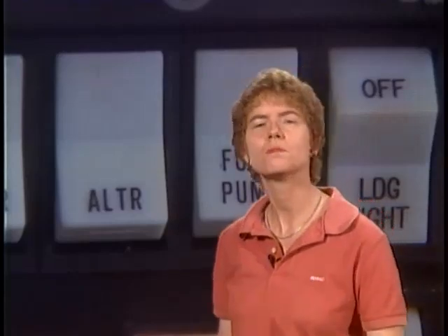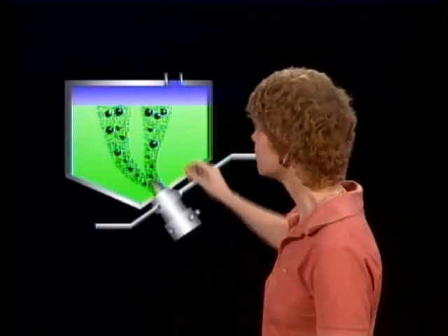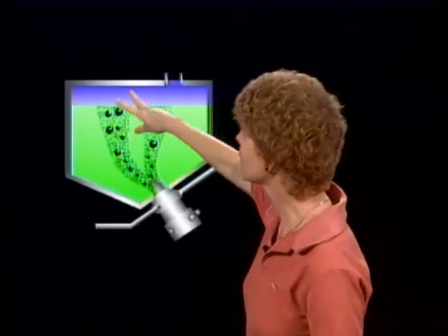Now, some boost pumps are a centrifugal type boost pump that is buried or sunk in the fuel tank itself. The centrifugal type boost pumps are used in fuel systems, particularly of aircraft operating at high altitude. They supply fuel under pressure to the engine-driven pumps, and they prevent vapor lock. Now, the centrifugal type pump, you should know, separates air and vapor from the fuel. Here's air and vapor coming out of that pump before it enters the line to the carburetor.